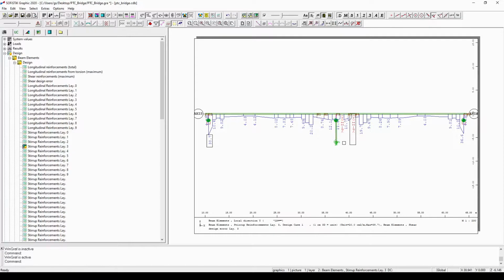For those kinds of shear cuts, the methodology for the shear design in the cracked cross-section is based on the difference of the longitudinal forces for the flanges. However, if we want, we can control the shear design procedure, and with the help of a text input, we can switch to a shear design that is based on the sectional values. So this is exactly what we are going to do.